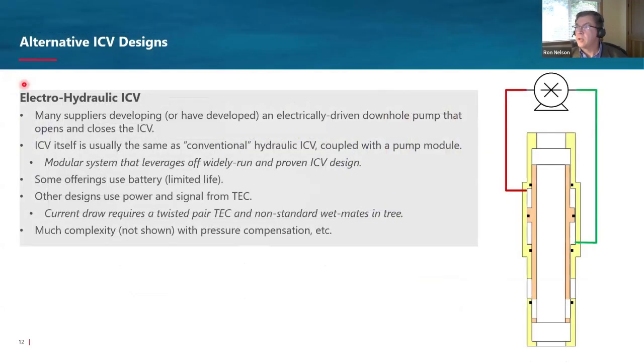Right, now we want to start talking. I was going to talk about some alternative designs of ICVs. One that's fairly new, I think there's 4 in the ground right now, and most of the vendors are working on this design, is basically taking, instead of that stepping module we were just looking at here, an electrically driven downhole pump and using that to open and close the ICV.